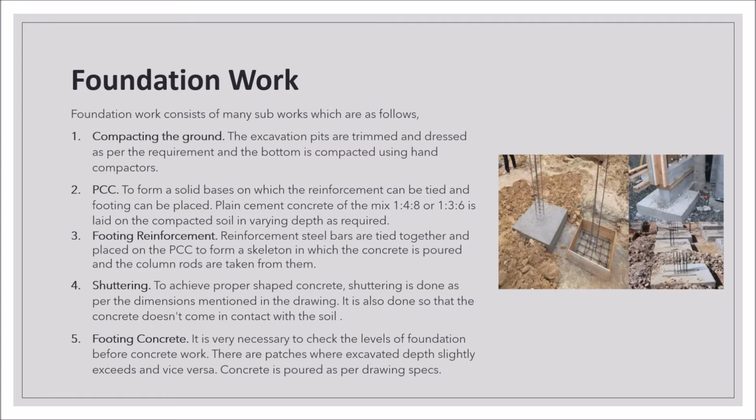Footing concrete. It is very necessary to check the level of the foundation before concrete work. There are patches where the excavated depth slightly exceeded, and vice versa. Concrete is poured as per drawing specs.